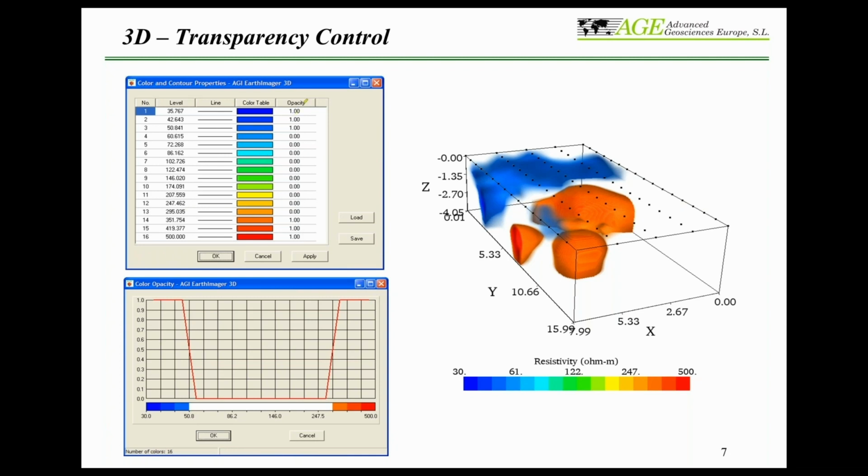From there, you go to opacity, and you will see the color scale of resistivities, and you can turn off any color or turn on any color over here. If you do something like this, you can get transparency because you're turning off almost all the high resistivities, giving more color options in the low resistivities. It will give you different kinds of images. So you can play however you like with the color rendering and volume rendering.